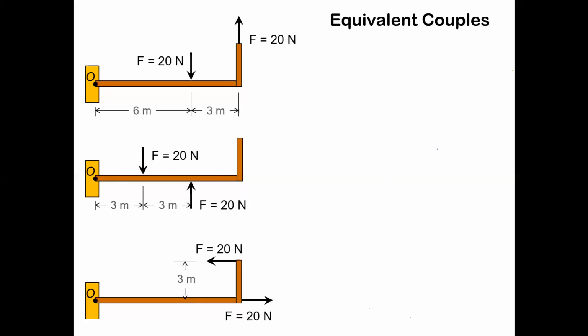It's just the force times the separation distance between them, and it doesn't matter where you apply it. That's the weird thing about couples: if you apply a couple to a body, the whole body everywhere is feeling this rotational sense. They call it a free vector because it's not localized. It's just the whole thing wanting to rotate. It doesn't matter where you look. It's not necessarily about point O, about point A, about anything else. All experience that desire to rotate.